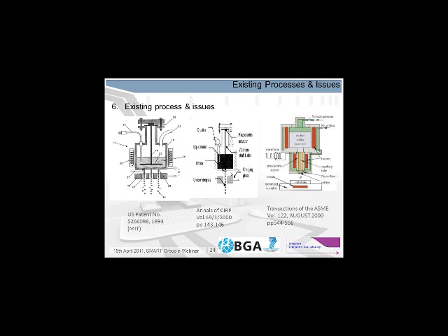You can see in this system here, the solder metal as it comes out is having a charge applied to it, so that the solder balls will repel each other and not bump into each other in the molten state, or even after solidifying and either join together to produce defects or to possibly damage each other.